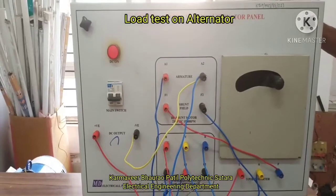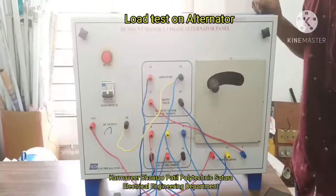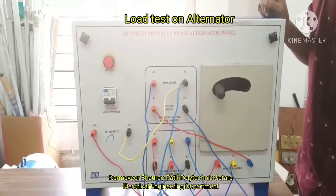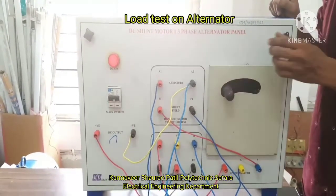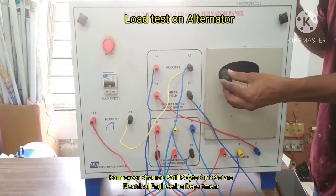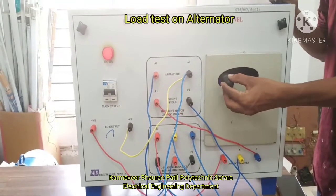After that, we will be taking the readings for inductive load. After making all the connections, now we will make the machines on. First, we will make the motor on. For that, put on the main supply switch, then rotate the starter handle to change the position of the machine from off position to on position.